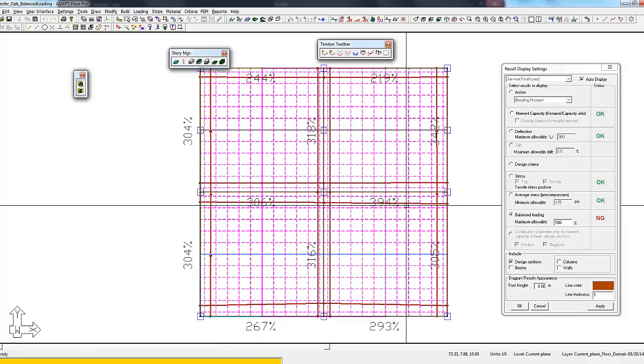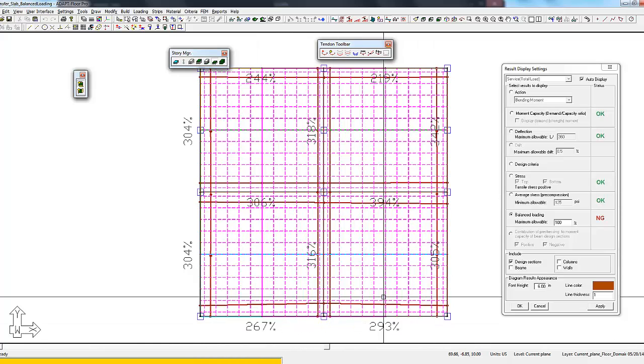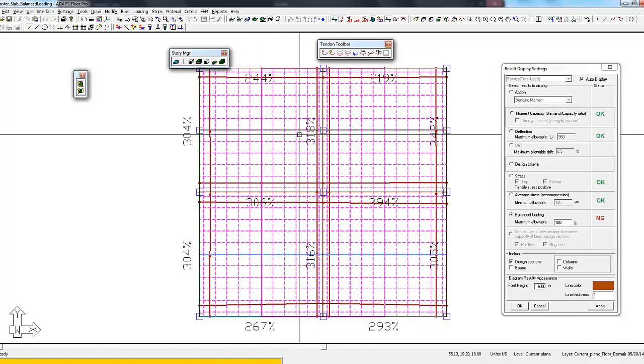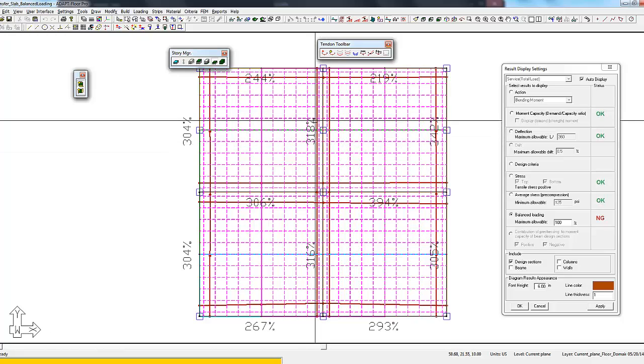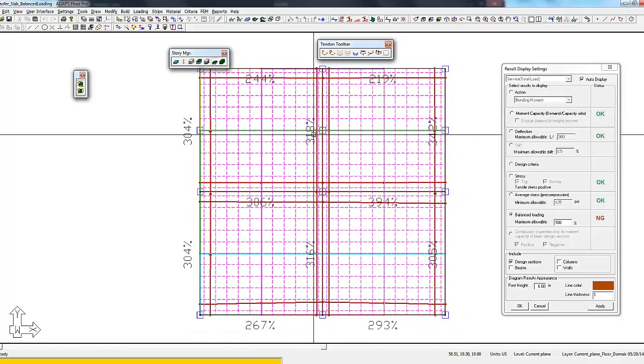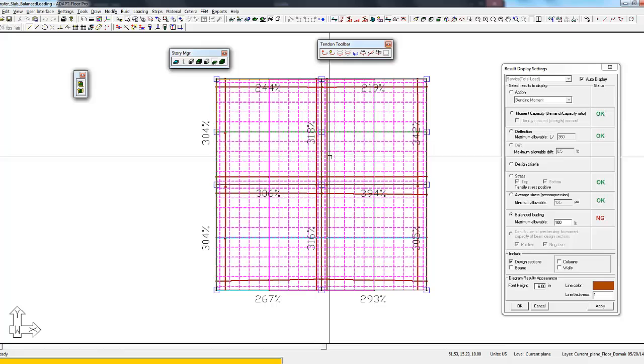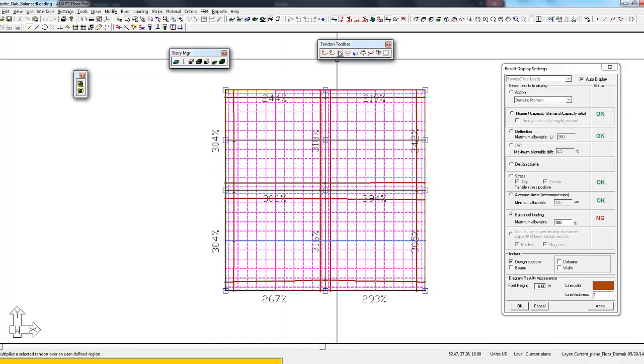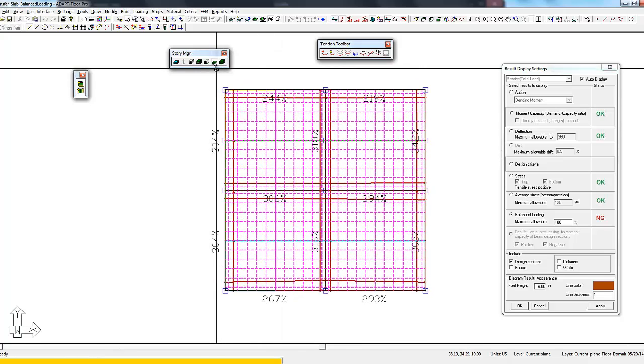Specifically here I kind of just threw in some tendons, and this is really not applicable, but here we have 318% balance loading. That's because we have a ton of tendons and we have very little load. We are not considering the transfer condition yet. So that's kind of our base level look at what the balance loading is.